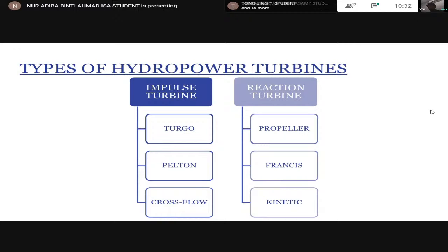In my opinion, there is no problem if you use Pelton turbine, since there is also research showing that even though it is a 15-meter head, we can still use Pelton, which uses a nozzle with a different diameter. So for a 15-meter head at Kota Tinggi waterfall, we can adjust the nozzle so the flow rate can be decreased or increased.